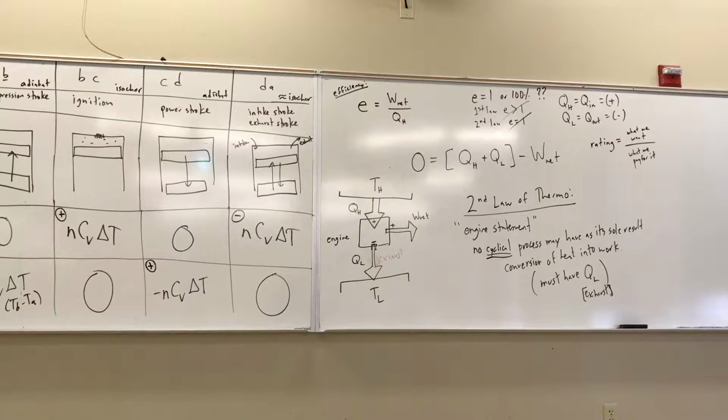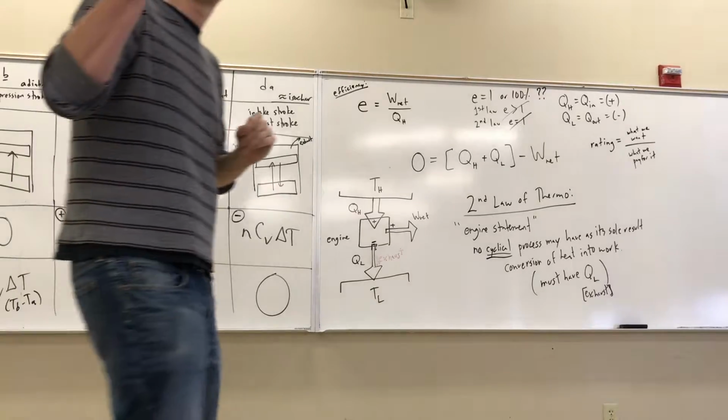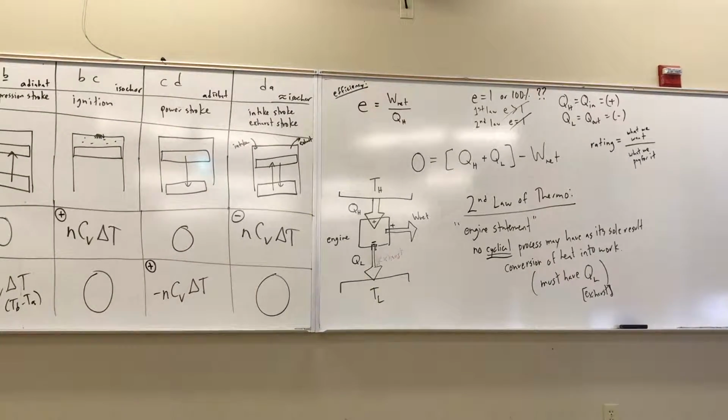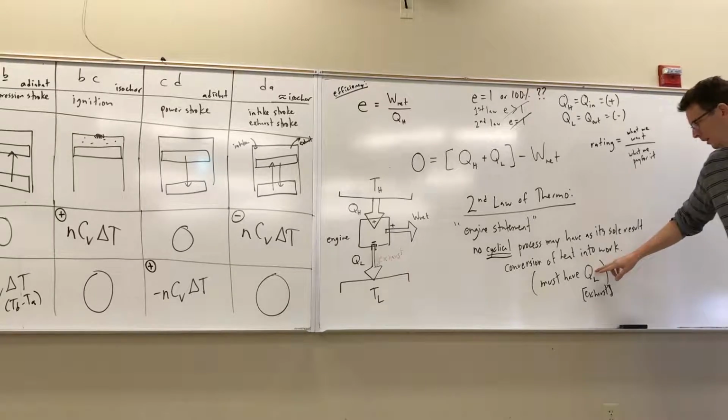Now, obviously I haven't rigorously proved this. I've shown this for a gasoline engine, but you can try it yourself, concoct whatever closed loop you want, and if you close your loop, then at some point you will find that heat is flowing out, and that's your waste, okay? It is impossible to have an exhaustless engine, okay? You must have QL, okay?